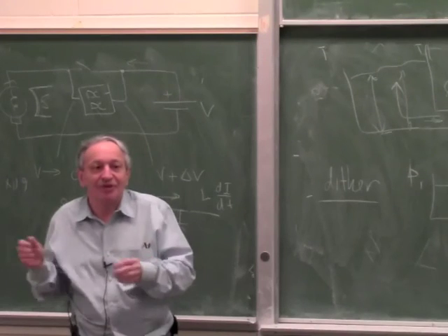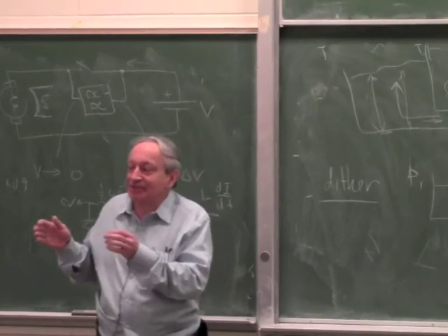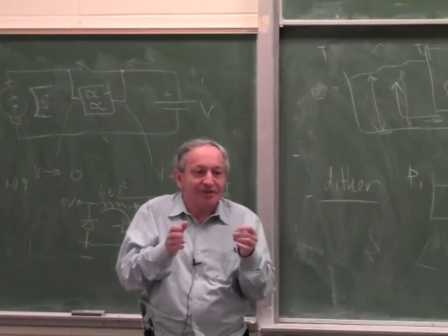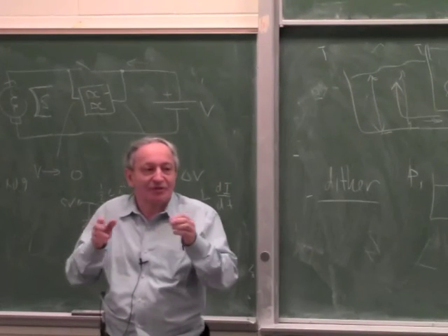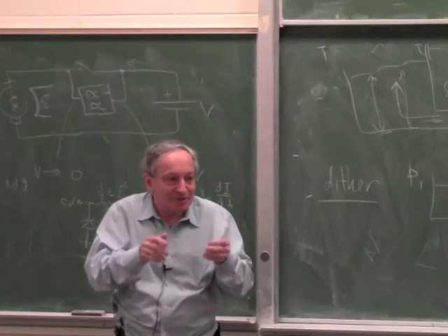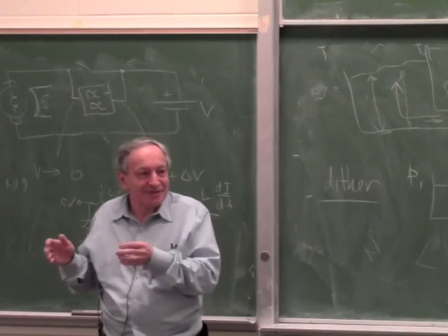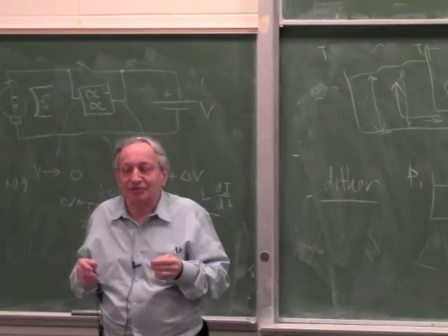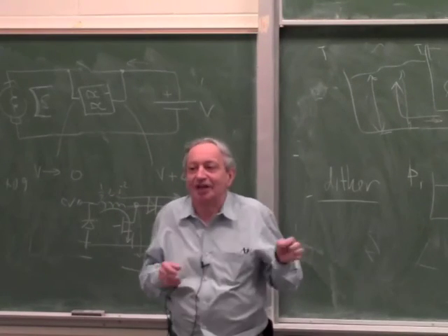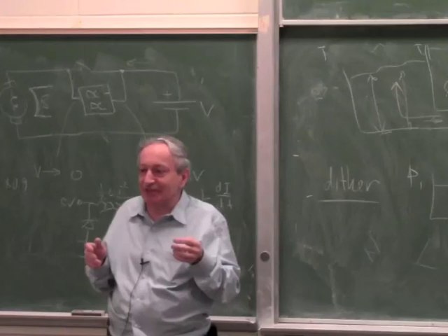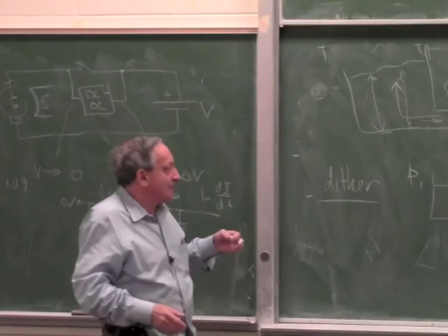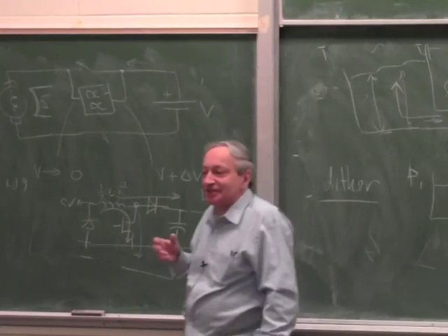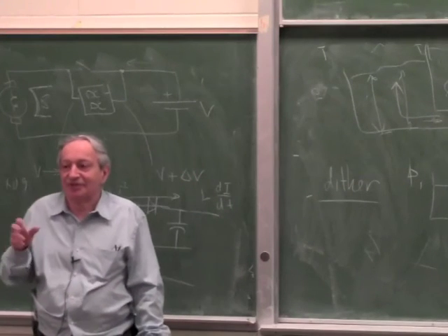If you have a piston, you want to make it go one way, you increase the pressure. You have to have a certain minimum pressure to make it start moving. Now you want to make it go backwards, you have to reverse the pressure and go a little bit below zero, right? Otherwise there is some static friction. And that's very bad for a servo, because we talked many times how bad backlash is for a servo, or hysteresis. So every hydraulic system with pistons and stuff has built-in hysteresis because of the difference between static friction and